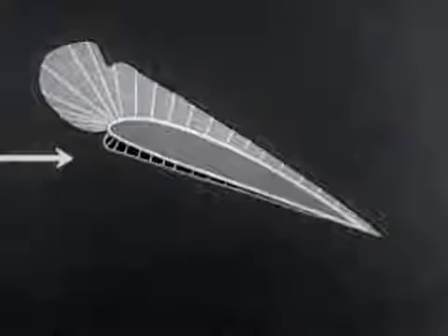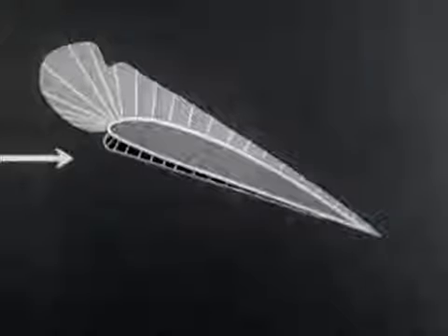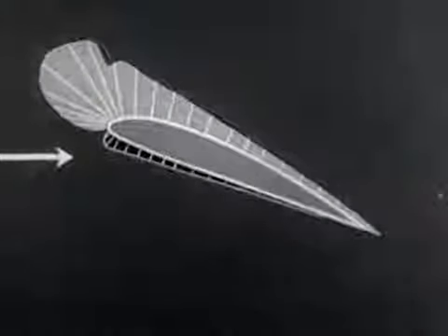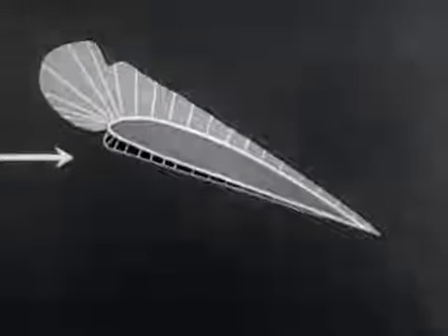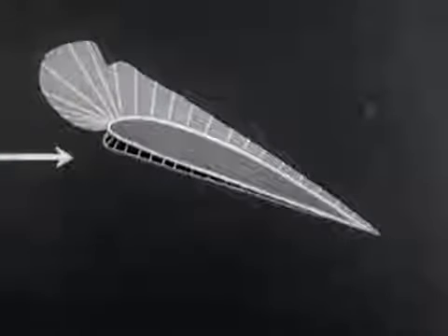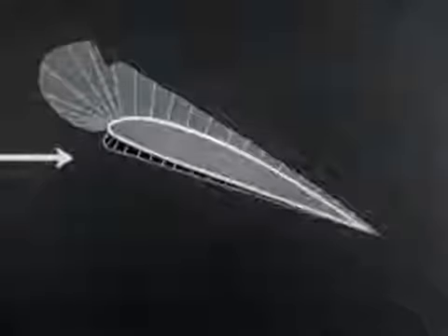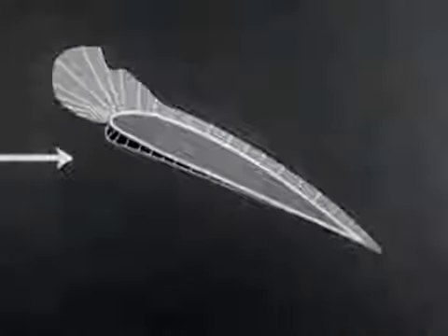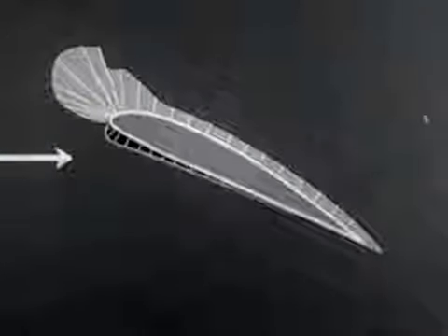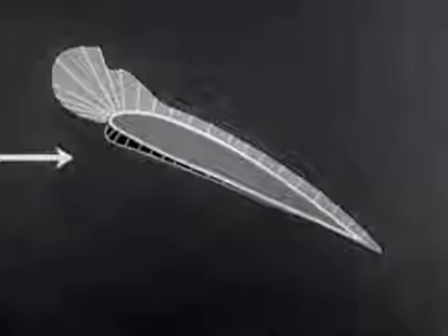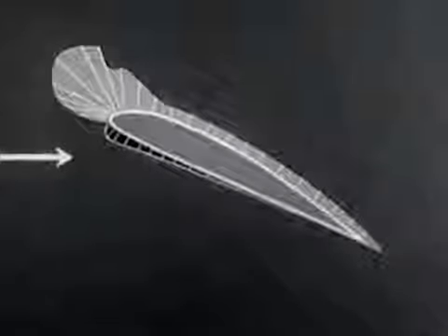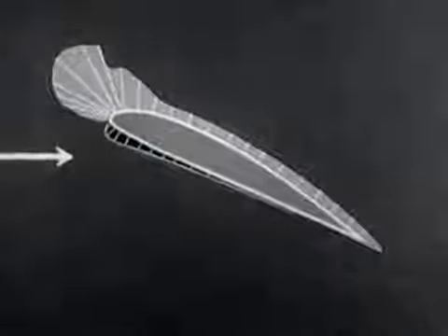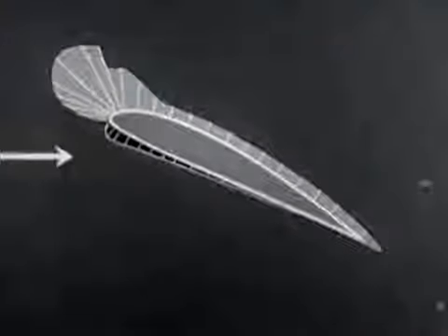With the negative pressures, the greatest change is noticed at the leading edge of the wing, where the area continues to expand, and the outline of the pressure area is extremely irregular. Increased angle of attack brings no important change in positive pressure value or distribution, but the negative pressure area is tending to equalize in value over the entire upper surface of the wing.